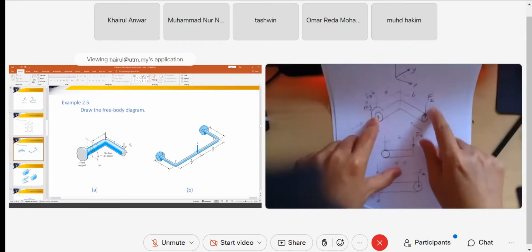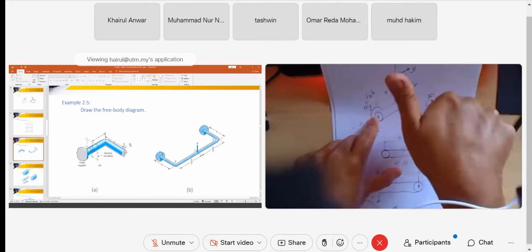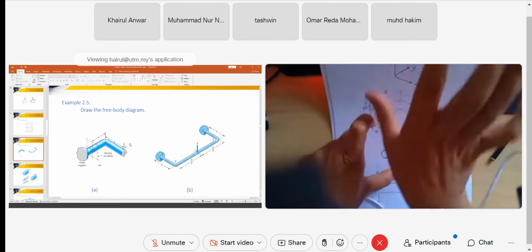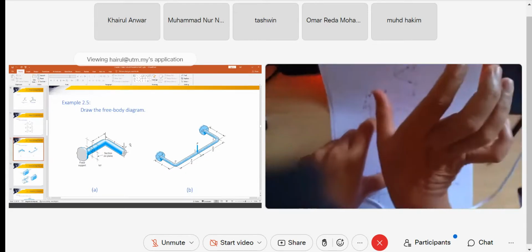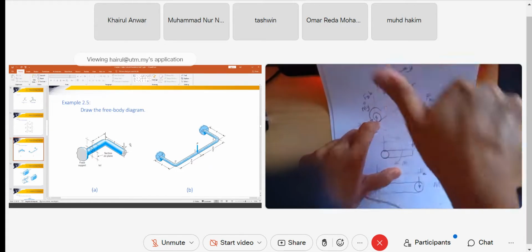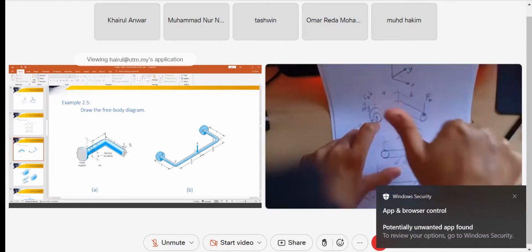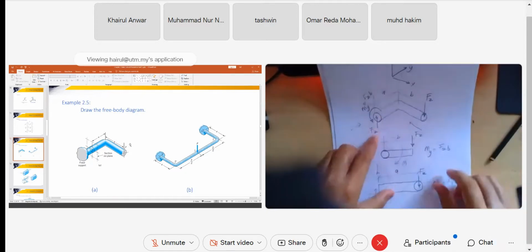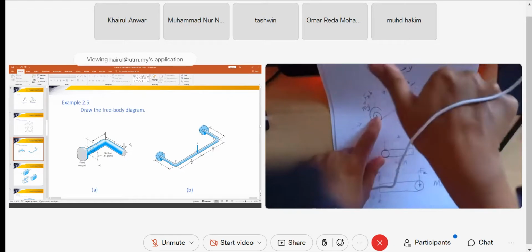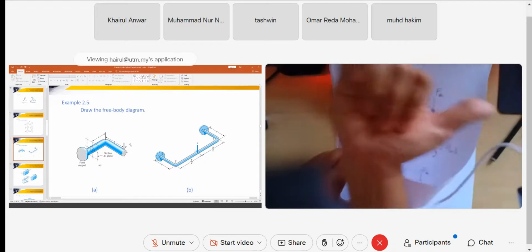The external FZ times A produces a downward twist direction. Right hand rule, the thumb is the vector. Do not confuse. This is not the direction of your moment actually. This is only the twist direction. The direction of your moment is the vector. This is the moment, not this one. But by right hand rule it goes to negative X. This one is the external moment. But at the end, we get summation of moment X is 0. So at the end, it must reverse. Must go to this direction.